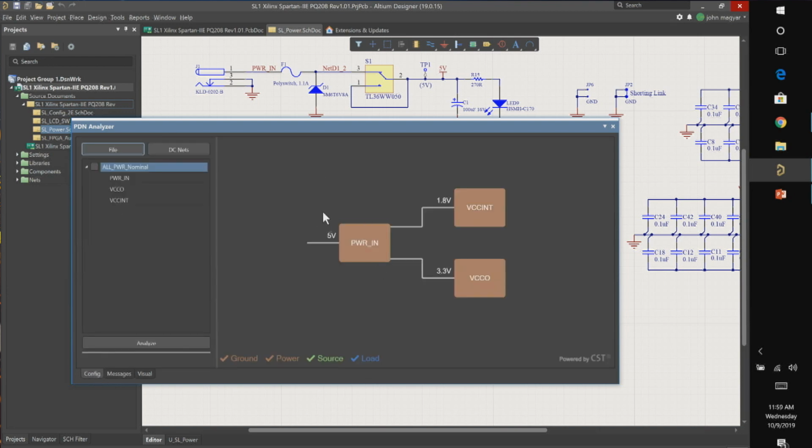In the configuration panel, at this point I'm ready to run the simulation. I always do a double check here. You'll see these green and blue checks. That basically indicates that the tool is satisfied that everything's been fully configured, and actually it does that in an order. It's order dependent. You can't get to the run button without satisfying these in a specific order. So it's doing some double checks to make sure you have an accurate setup. I'll go ahead and hit the analyze button.